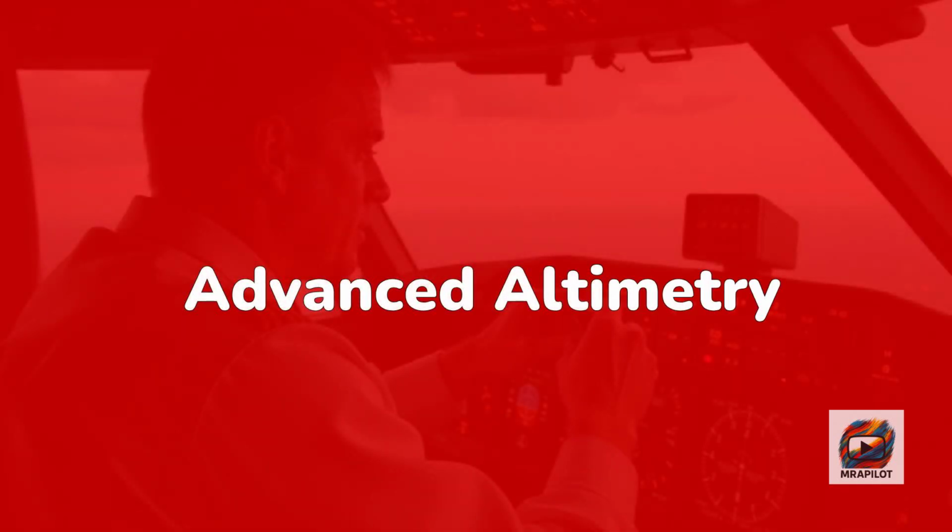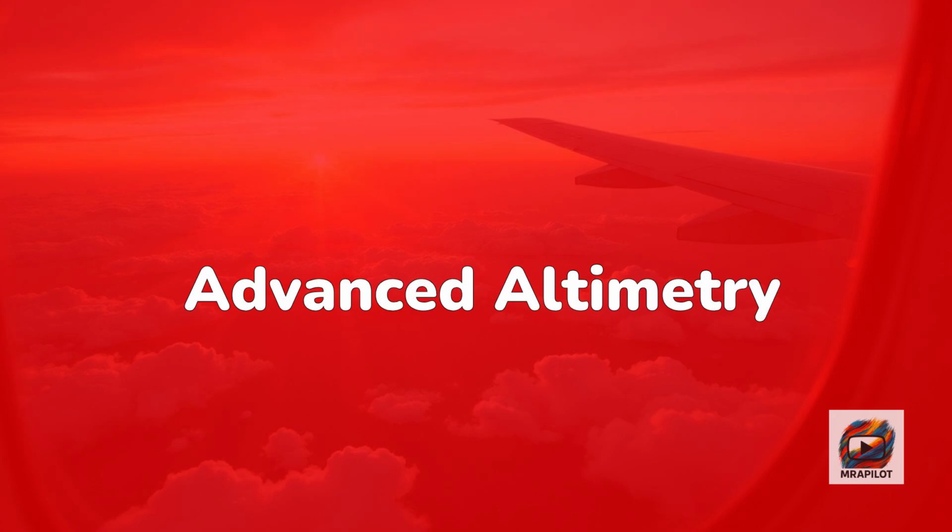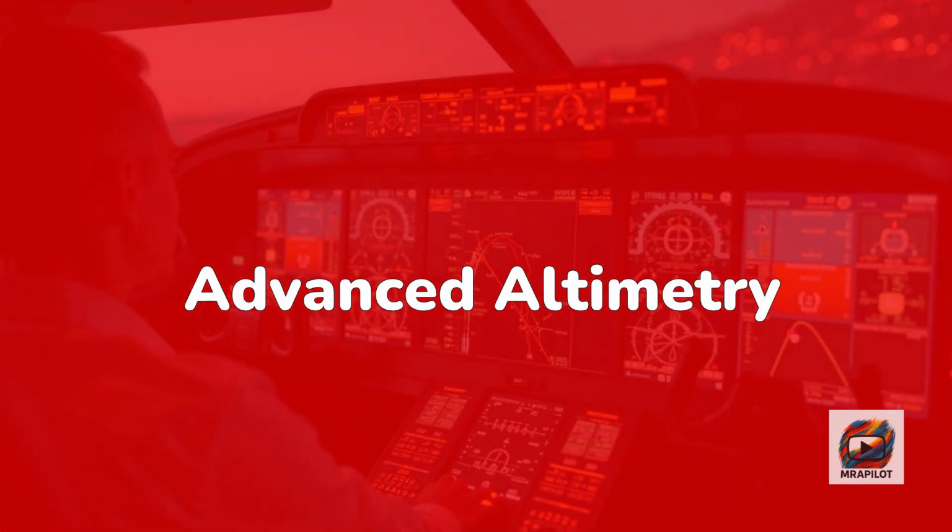Welcome back. In our last episode, we explored the basics of altimetry, how altimeters work, the meaning of QNH and standard settings, and why pressure and temperature matter. Now let's continue with advanced altimetry, including RVSM, vertical separation, and modern navigation systems.